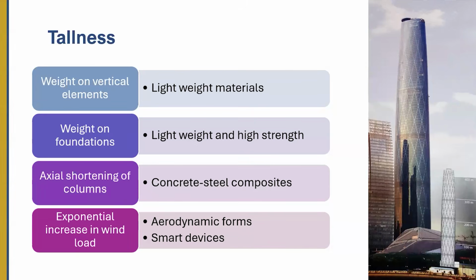Of course, in reality, this doesn't happen. Why? Because when they're making the floor, let's say they're on the 40th floor, whatever shortening has happened already, they will level it off. Which means the columns are actually made longer than the core wall, and after they shorten, they become level. So this is something that we call the construction sequence analysis. So you have to do a special analysis to capture this effect, where the columns are actually made longer on site than their actual length. And after settlement, they become equal to the wall.